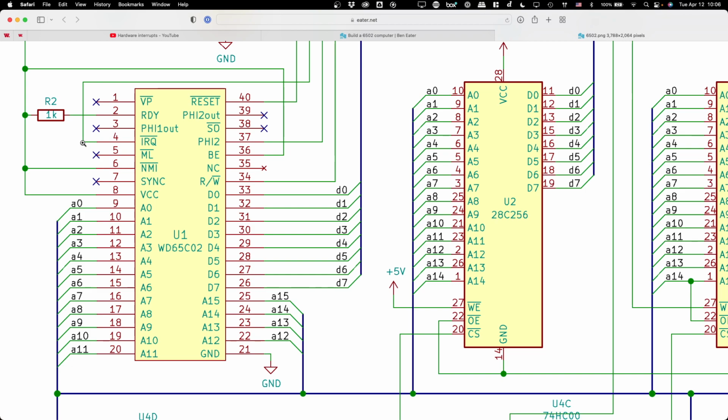Or if you're operating it at a high frequency, like in his videos, he's using the 1 megahertz clock. So it's like thousands, right? And even if you just barely tap the button, you still get hundreds worth of interrupts because the thing is just operating that quickly. Okay, so that clearly is not the way that we want to deal with the interrupts. We don't want it to be triggering hundreds of them when we just want to read it once.